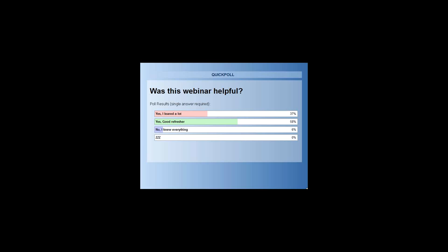So I hope that. If I can add to that, Larry, I would say at an isolated signal, something like dilemma zone detection can go a long way. Yeah, that's true. Dilemma zone detection, being able to actually extend the yellow a little bit further, could go a long way. But again, if the guy in front is fairly passive, sees the yellow and hits the brake, and the guy following closely behind him sees the yellow and hits the gas, something's got to change there. So that would be a good thing, dilemma zone protection, and again, just making sure your yellows and all reds are adequate for the speeds people are really driving.